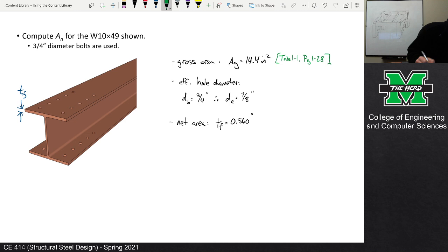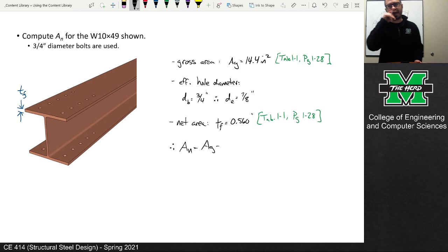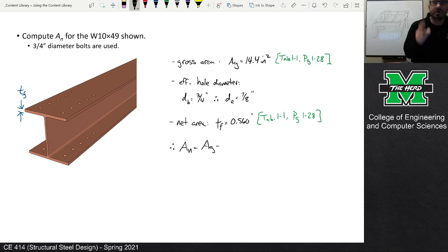Well, hold on for a sec. I'm going to get to Mr. Roman's question in a second, and you'll see where I'm going with that. So 4 times the diameter times the thickness. The reason we're doing that is, again, imagine samurai or lightsabering through the section.